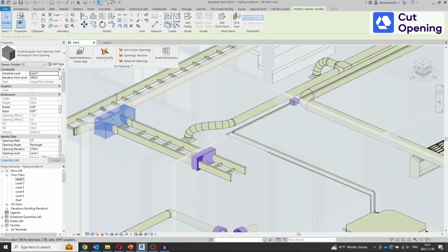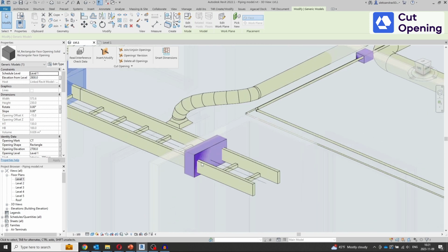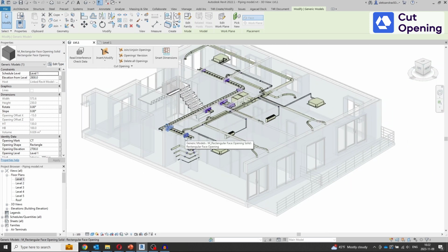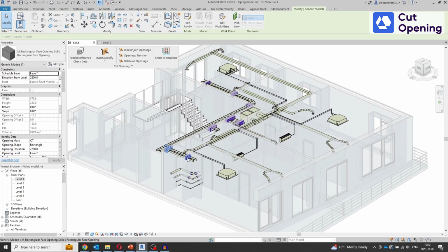But don't worry, if that is needed, you can tell our tool to ignore places where fittings clash with the structures. Also, if it ignores those, you can choose to see those places without inserting the openings. Further, with cut opening, you can achieve even more. For example, here I have set additional offset for the cable tray opening on top so that the cables would fit. That's a regular practice. Okay, finished with cable trays, let's move to the ductwork. That one sure will take longer.